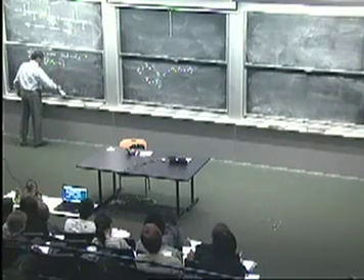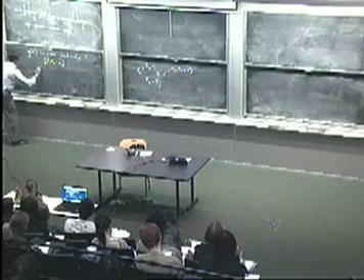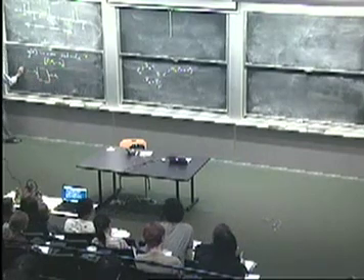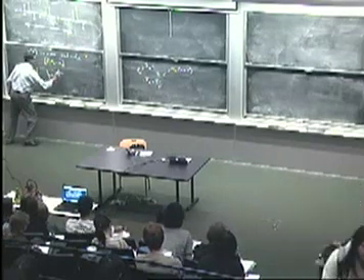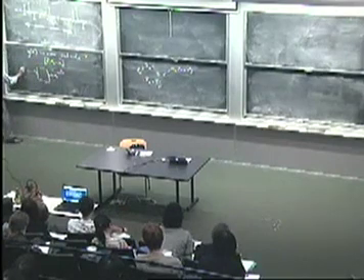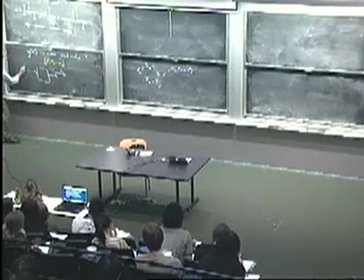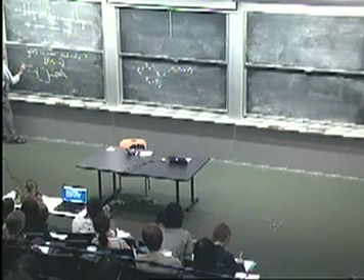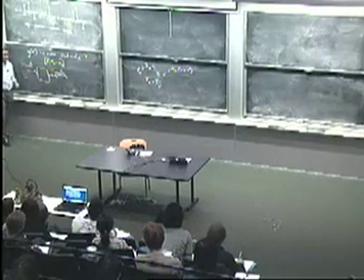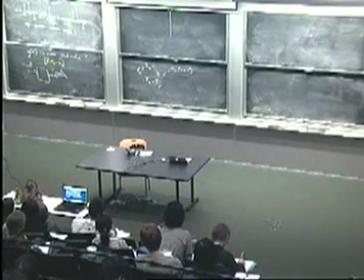There are many ways to think of this. One is to say, well, the input value at time 0 fires off a unit sample response that goes from 0 to n sub h, and then the input value at time 1 fires off a unit sample response that starts one time later, and so on. So each of these fires off a unit sample response. Well, you've got inputs extending from 0 to n sub x, and so you're going to have an output that extends from 0 to n sub x plus n sub h. All right? So you're guaranteed that all the action of interest happens in this finite interval.